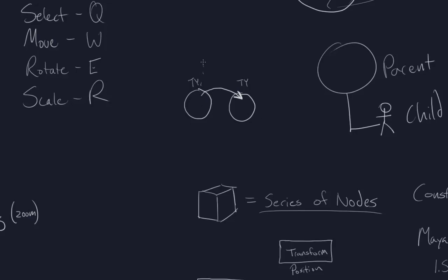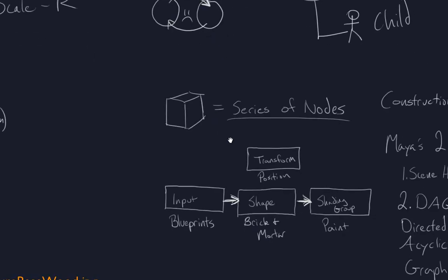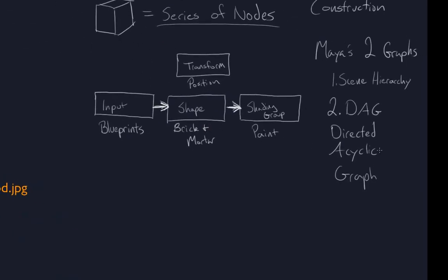That means when I move this sphere up, this one will move up too, which is great. But if I then tell the translate y of this sphere to go back and affect this one, we have a problem because that's a cycle, and Maya will not like that. And it still does look like glasses, I know, at least for a minute. That's because Maya's architecture is acyclic. It doesn't like cyclic relationships, and it will start to act funny if you create one even by accident.